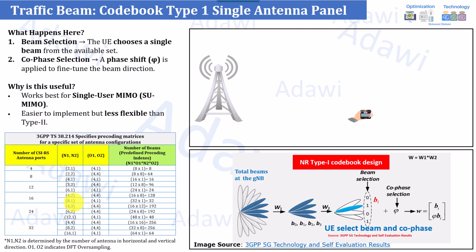For example, in the network, you can give two inputs, and based on these inputs, you can define how many codebooks we have, which define particular beams, which can later be decoded by the user in the downlink direction through reading the CSI-RS. He will report back to the gNB, telling it that this is the best precoding matrix for me, which can maximize my signal to noise ratio. So initially, from the configuration point of view in your network, you need to select one of those configurations.